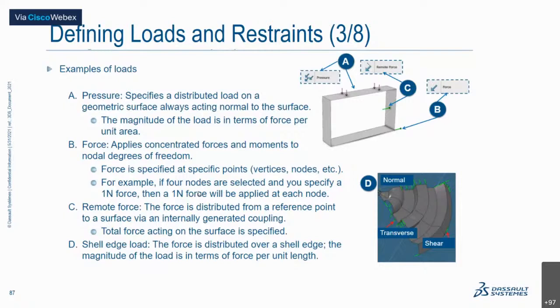Again, remote force. So remote force is something where the location where the force is going to be applied will be decided by the system based on your selection. So the total force acting will be selected. You'll just have to give the total force that is acting, and then based on the selection you have made, the force will be applied to it.